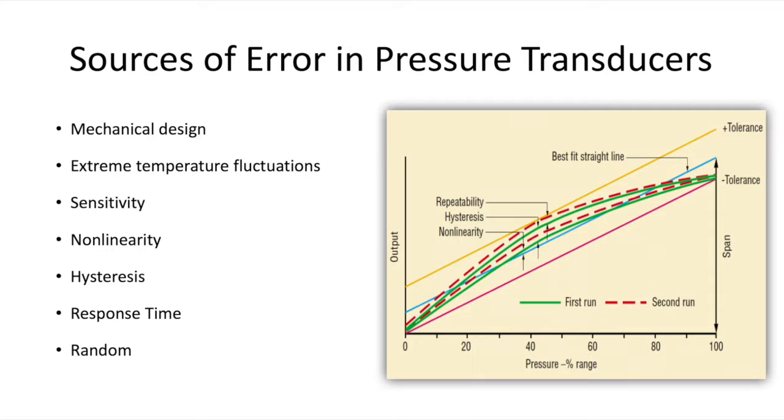Offset errors. The offset error of a transducer is defined as the output that will exist when it should be zero, or alternatively, the difference between the actual output value and the specified output value under some particular set of conditions. If an offset error exists, the actual and output data will not match. Response time. Sensors do not change output state immediately when an input parameter change occurs. Rather, it will change to a new state over a period of time, called the response time. This might cause error by simply not reacting fast enough to record a data point.